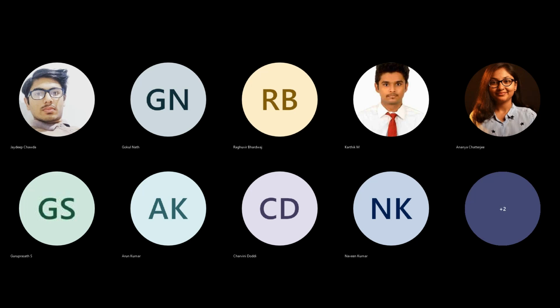So we have to select our separation process based on the nature of our product from the reactor. For example, if solids are suspended in liquid or gas, then we will select the separation technique called filtration. Sometimes we can go for settling or sedimentation, sometimes centrifugation. If it is gas-solid, we will go for cyclones. So we will select these types of things.